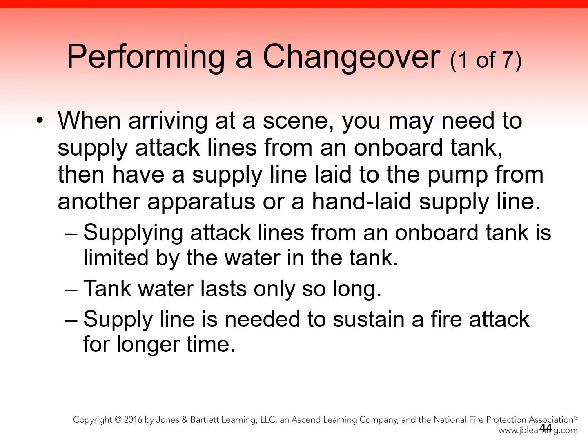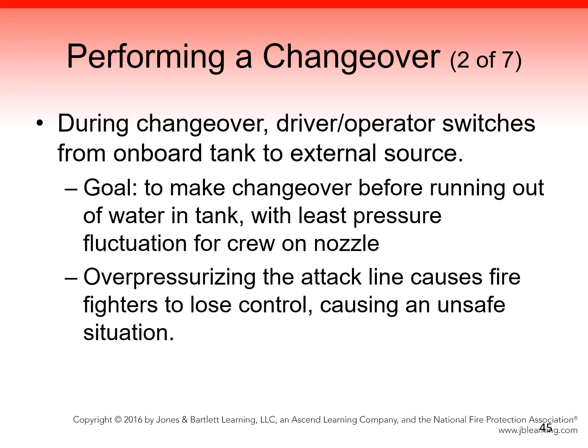attack for longer periods. It is wise to recognize early on that the amount of water flowing through the attack lines is or will be far greater than the amount of water carried in the onboard tank. For this reason, it is important to establish a supply line early and to perform a changeover operation. During a changeover operation, you switch from the onboard water tank supply to an external water source.